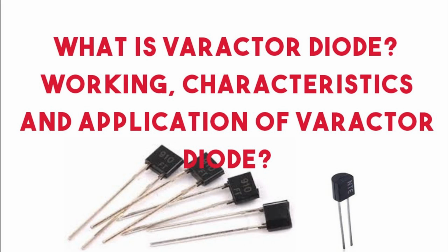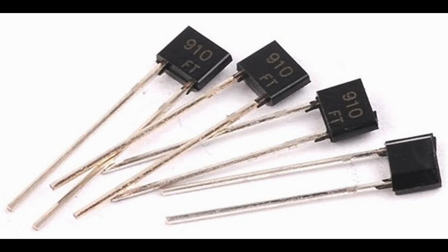4. Examples of VCVS. Operational amplifiers. Op-amps can be configured as VCVS by connecting their inverting or non-inverting inputs to the control voltage source and using appropriate feedback elements. Multiplier circuits. Some specialized circuits are designed to perform voltage multiplication based on control voltages. Voltage-controlled oscillators. VCOs generate output voltages that vary based on control voltages, making them a type of VCVS.